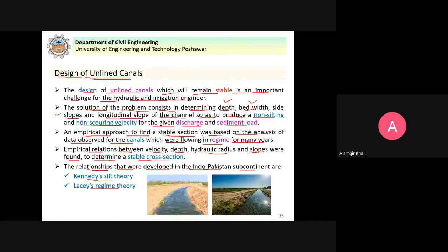We also have design of lined canals. For the lined canal, the same approach applies as you studied in your hydraulics course. You use Manning's equation, the Chezy formula, and then you have the most efficient cross section, etc. So that approach is used for the lined canals.